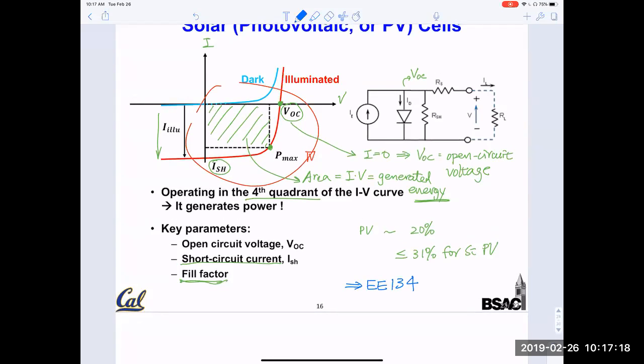So this concludes our discussions of all diodes. So in summary, we talked about the device physics. What are they made of? What's the origin of the current? The circuit model, exponential circuit model, we derived it. How to solve the DC bias. How to solve AC circuit that has a diode in there. We talked about large signal behavior, like rectifier, converting AC voltage into DC voltage. We talked about the peak detector, negative peak detector, level shifter, and so on. So those are kind of common usage of diode.